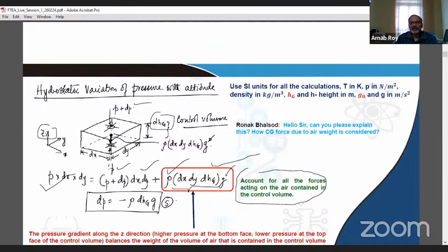As you may recall, when we looked at the geopotential approach, it was one way of defining the G, while when we talked about the geometric altitude, we talked about a different value of G. In one case, we referred to the G at sea level as the reference, while in the other, we referred to it as changing with altitude, and therefore this G would actually become a function of H. And therefore, a slight difference in how we interpret things.